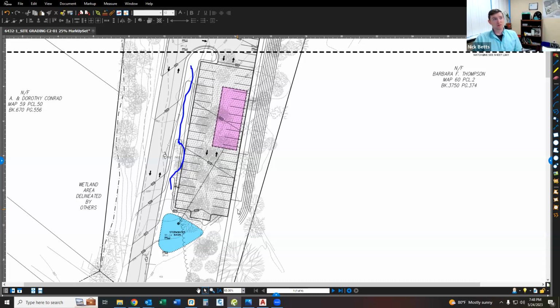If possible, I don't know if that system could be upsized at all. I think I'd have to have a discussion with Greg about whether he maxed it out to capacity, or is this something that we could add a pump chamber to and a second feed. Short of that, you have the expensive sewer connection, and short of that, I think you're looking at a tight tank, in my opinion.